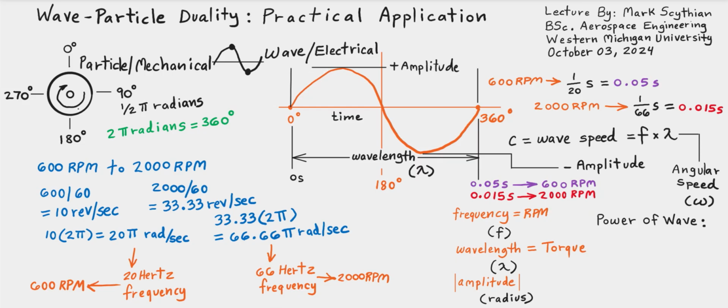Well, if you had an out of round condition or missing material below the tolerance, this amplitude would drop a little bit, and then you get a little red flag, a little yellow triangle with an exclamation mark in it. It's all because of this amplitude drop.